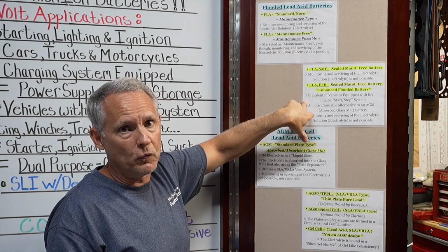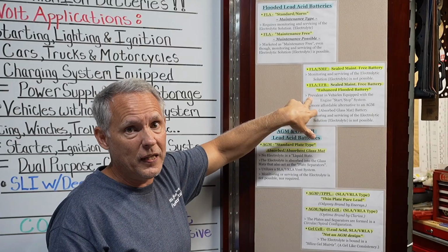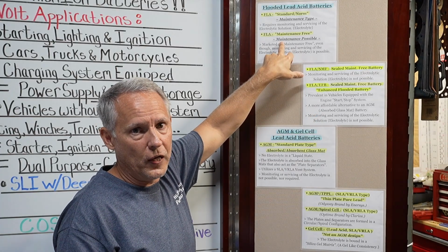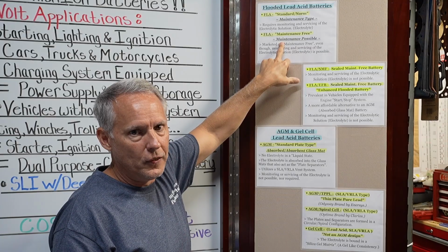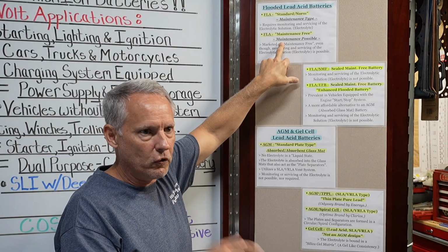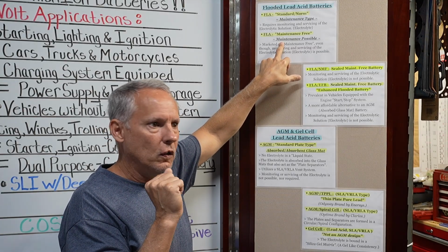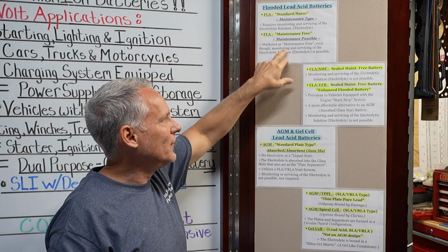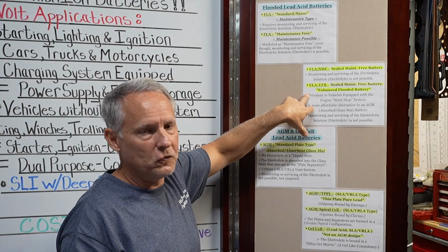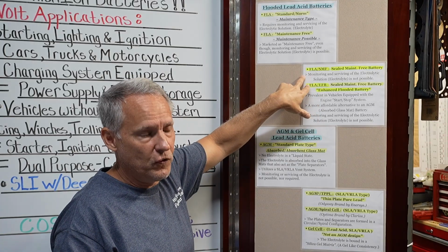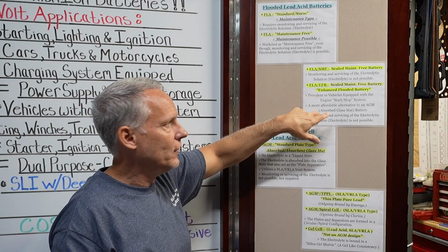If your vehicle comes with a start-stop system and it had a factory EFB, do not replace it with a standard FLA battery. It'll be an affordable alternative for you, but it probably won't last. It can't take all that high current discharge and recharge over and over and over. It's not designed for that kind of cycling. So an EFB battery is the choice. Don't replace it with something else, even though other batteries would physically fit. Don't do that.